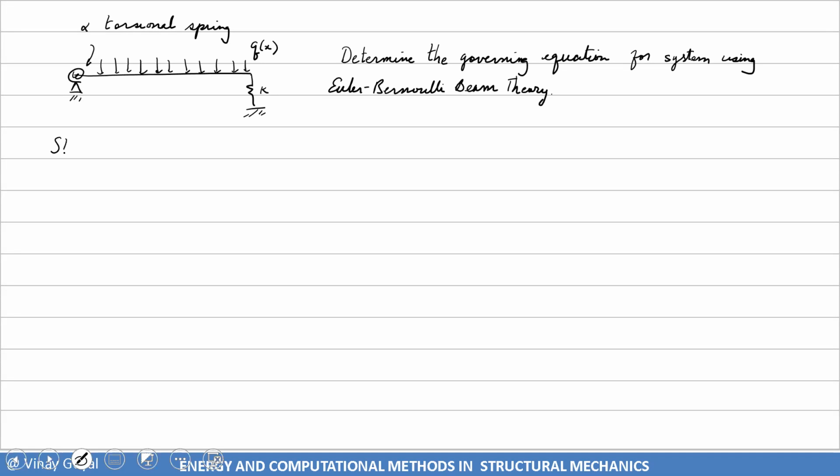Step one, we want to examine what the displacement assumptions are for this theory. In this theory, we're going to assume that there's no axial deflection, so it's all due to bending. Okay, and then the out-of-plane deflection is 0. The transverse deflection is w, and all the axial deflection is only due to bending, the slope.